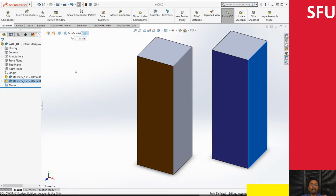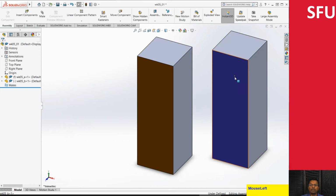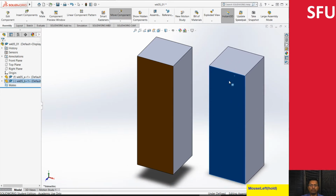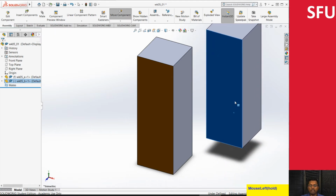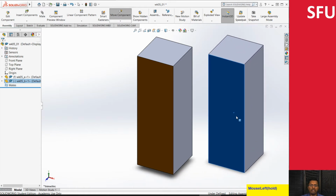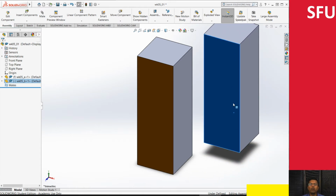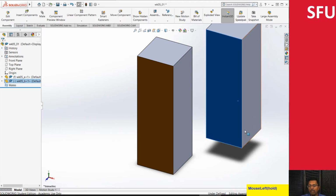And it's usually not a great idea to fix all of your objects in your assembly because eventually you want to assemble or mate these together. So let's float the second object and then now you can move it together. SolidWorks also assumes that the lowest object is placed on the floor, and based on the lighting, you can see the shadow changes, which is a cool feature to visualize what's happening, and also to get a sense of how far the object is from the ground.